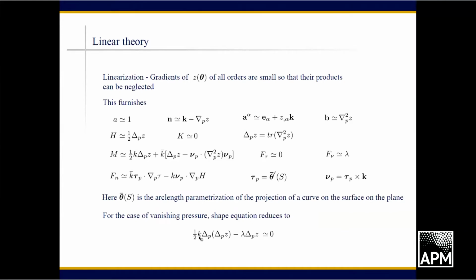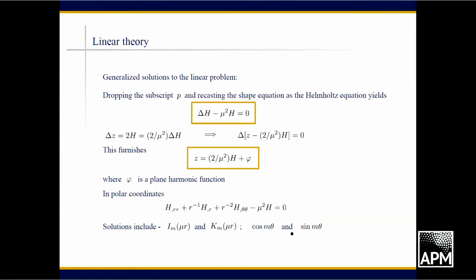And here it is at the bottom. K is a bending modulus in the energy. The subscript P refers to a Laplacian on the plane, not on the film itself. And lambda is the Lagrange multiplier we studied before. This is simply the classical, elementary plate bending equation, with an in-plane surface tension or compression lambda. And it's a simple matter to solve that.